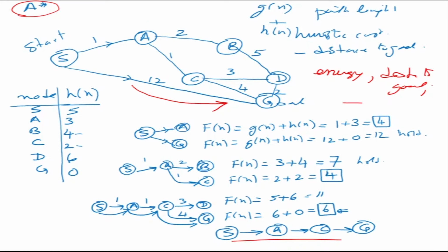Now suppose we have already assigned weights and the straight transition like this, but when the robot is traversing, suppose there is an obstacle. What the algorithm can do is raise or lower some of the transition costs.